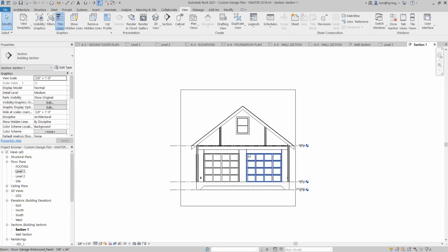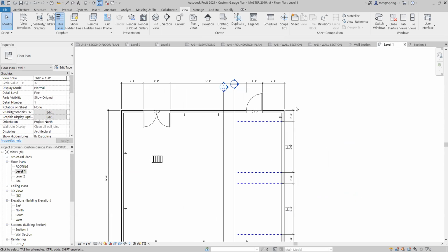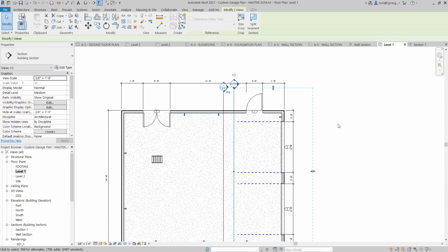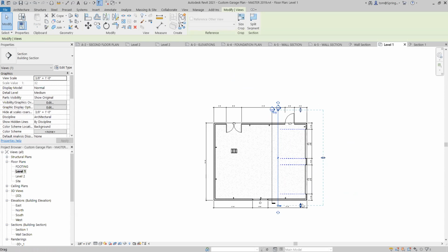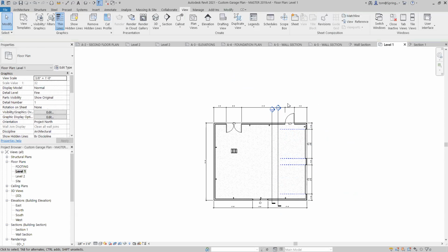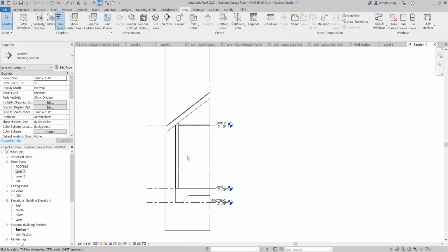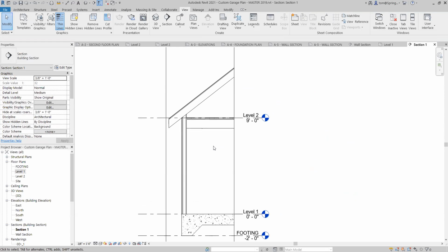Okay, that's a lot of information, more than I need, because it is giving me some information that I do not want. So go back to here. And what I'm going to do is, as I click on this right here, you'll see that the area that's defined by this one is much larger. So therefore it's giving me a lot of data that I don't want. So I'm going to go ahead and just make this smaller like the other one was. I'm going to pull this down, pull it back in like that. We got that. I'm going to double click on this, and when I do this, boom, boom, now this is what it looks like. So when you actually do your section view, this is all you're going to get.